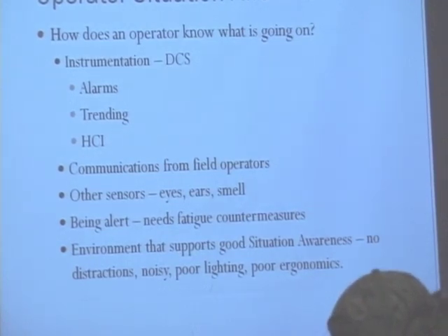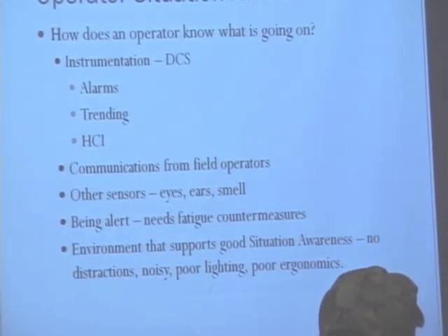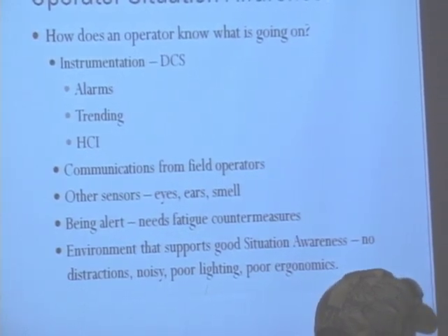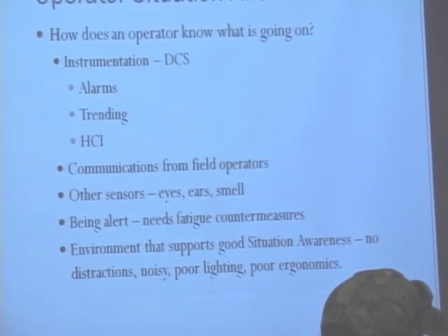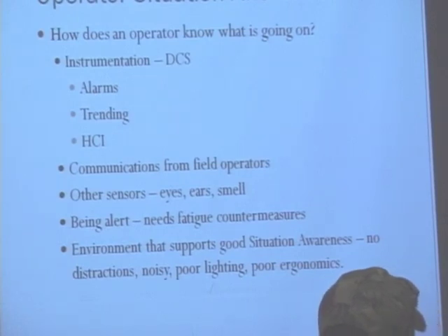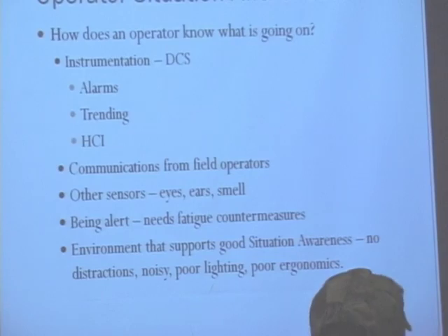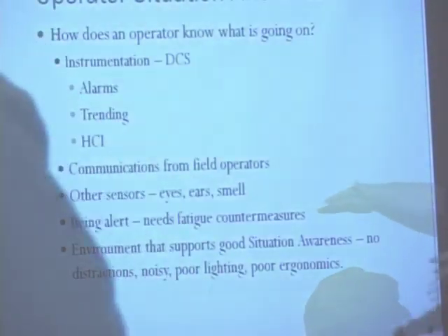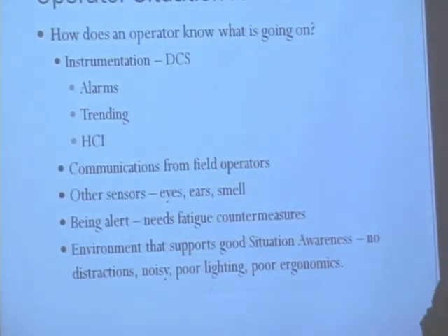Today we can use acoustic sensors to actually detect those noises and bring those noises in the control room, and we can actually bring them in on a microphone. So if the noise changes, we can audibly bring that noise in the control room. We can audibly detect it and then switch cameras so you can actually look at something as well. So there's lots of things we can do today to improve situation awareness. Basically, we need to think about fatigue and what are the countermeasures today that we can use to address those fatigue issues so that an operator is alert and ready to take action.